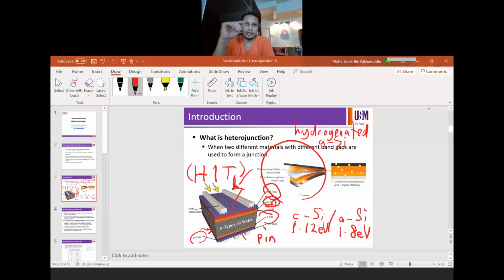We have learned last time that you can either have non-metal contacts, which is TCO, or you can in fact use metal contacts on your semiconductor. But in this case, Panasonic, they use metal contacts, usually silver here, metal contacts on TCO. Why do you think they use both types of contacts?